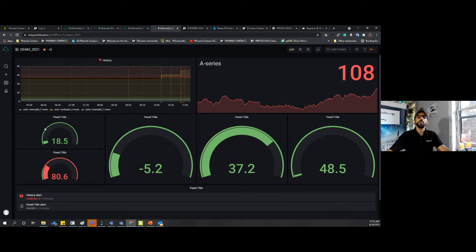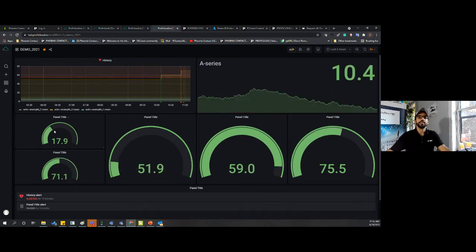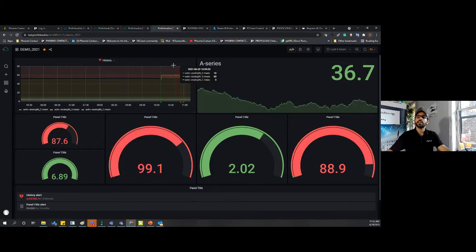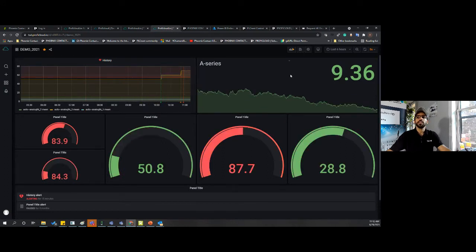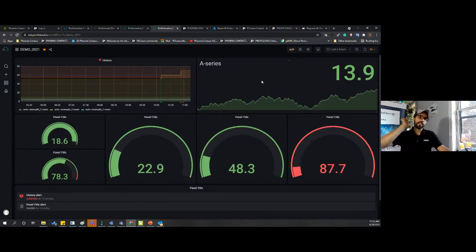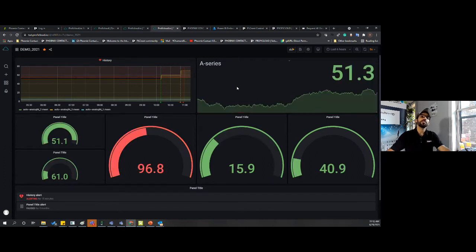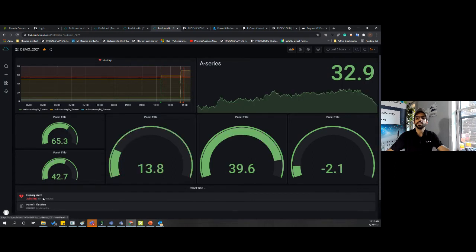I can do what we call single status, and those could be gauges, or a square that changes colors and things like that. And we also can do alerts. So if you have a trending bar like this one or this other one on the right, you can associate an alarm setting to that historical data. Let's say that you're monitoring a sensor that goes all the way up to 50 degrees. If it goes over 50 degrees, you want to get an email. And you can see that my alert right now is activated over here.